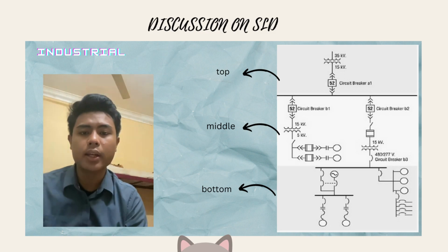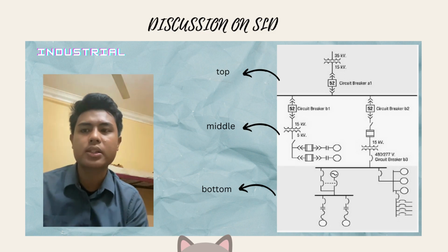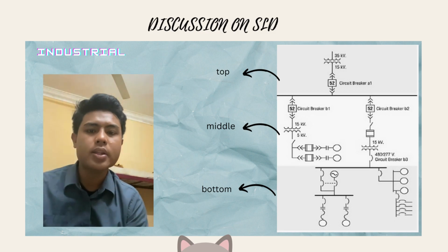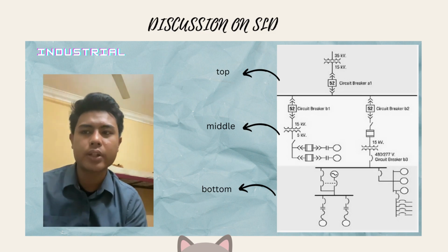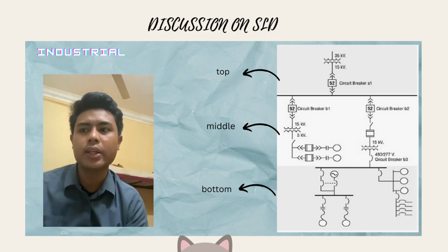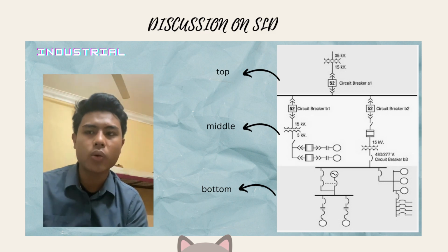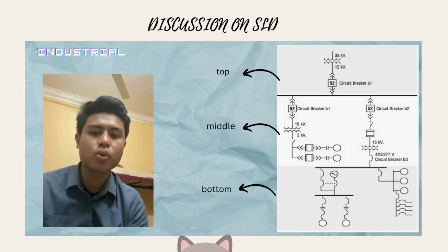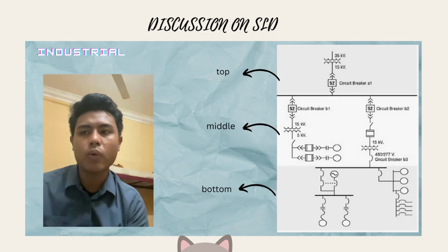Next, the single line diagram of industrial also provides the automatic transfer switch, marked as a circle in the single line diagram. It symbolizes the emergency generator. This section of the single line diagram shows us how crucial it is for the apparatus linked below the automatic transfer switch to continue working even when the power is lost.